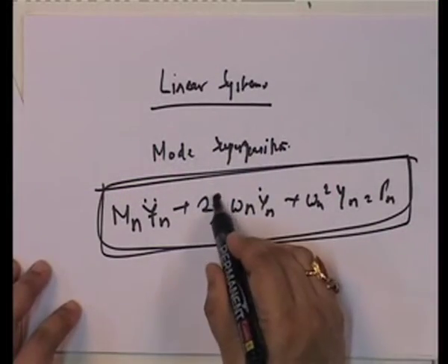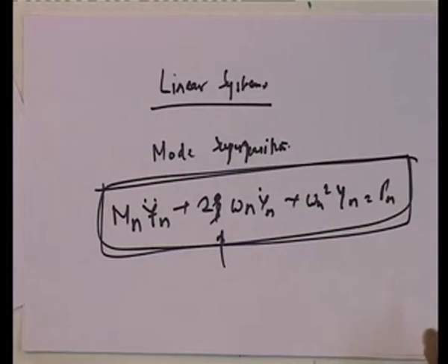If xi is the same in all the modes, then who cares? In a way, you may say that by taking xi, I am assuming Cauchy damping. You can say that, it doesn't matter. But you do not have to evaluate A, B. You say that you are considering Cauchy damping, but that is also irrelevant. You are solving modal amplitudes and you are assuming xi to be the same in all the modes. This is an assumption.